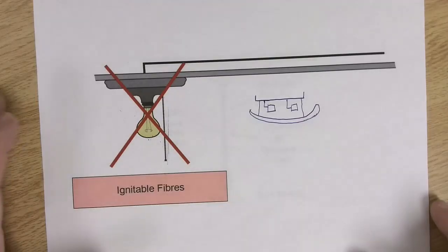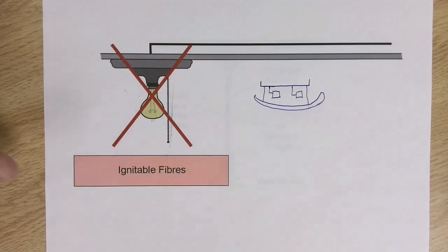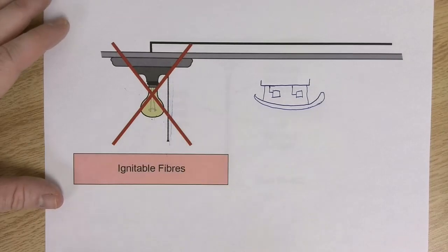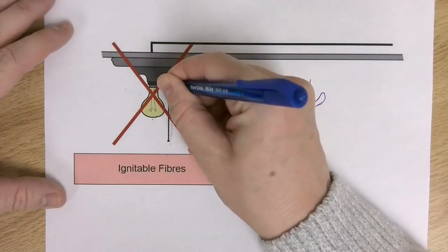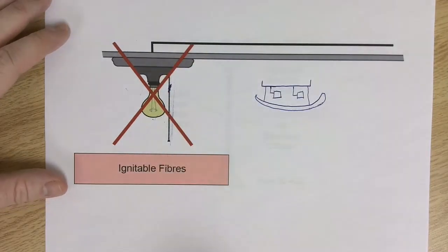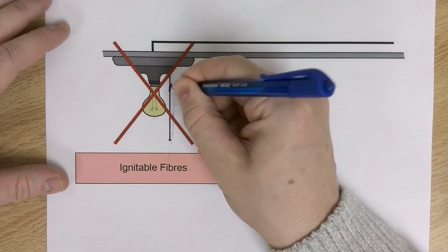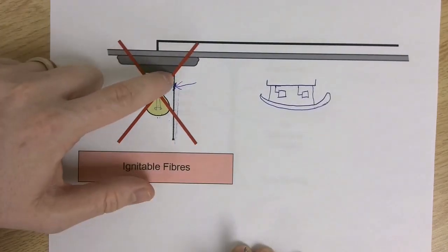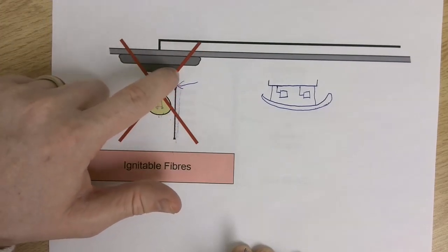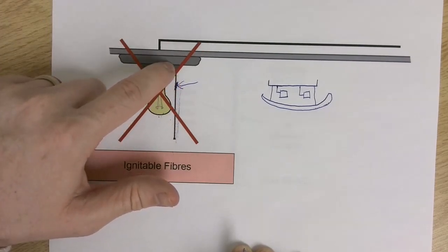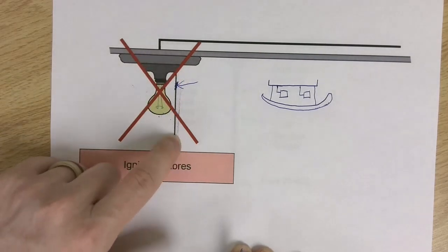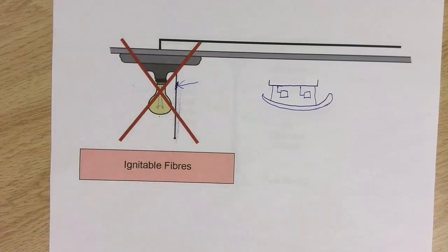Now, one thing that is missing from this picture from before, for this pull chain keyless lamp holder, is that part of this chain will be insulated. So that should this part inside, which is all metal connected to itself and uses the switching mechanism, for some reason become energized, when you go to turn this light on and pull this chain, you won't get electrocuted.